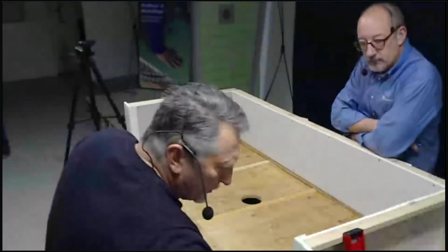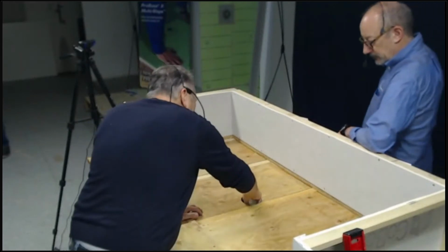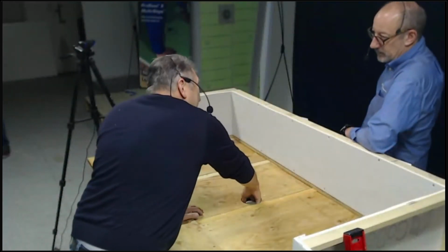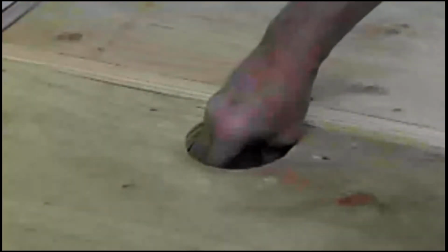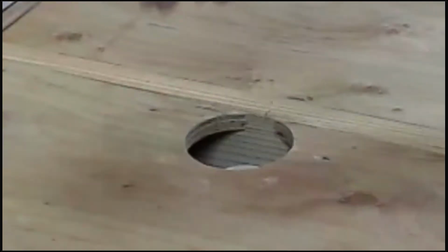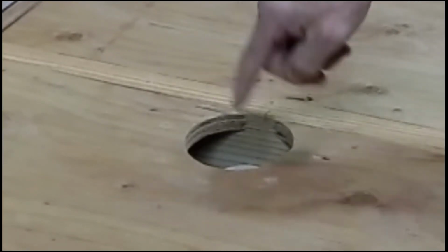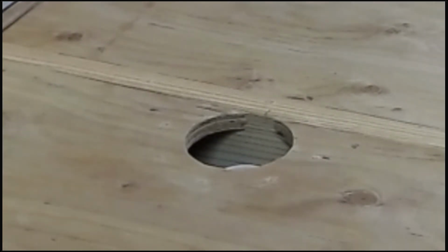So from here, we're going to add our stub. Had to lower that since we lowered the floor. Yep, let's put the lowest one in. Again, our stub needs to be 1 3/4 inches from the substrate down to the stub, top of the plywood to the top of the pipe. 1 3/4 inch, correct.